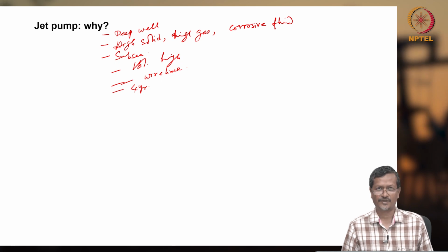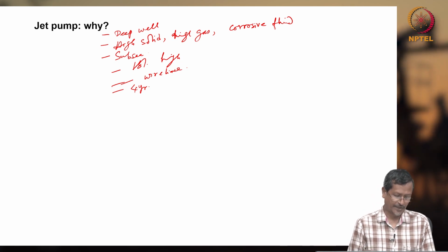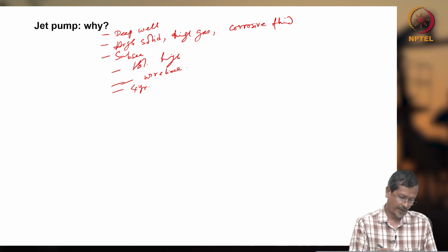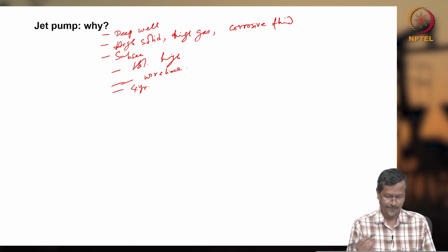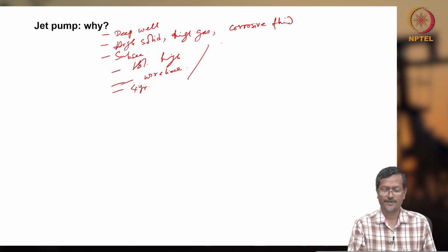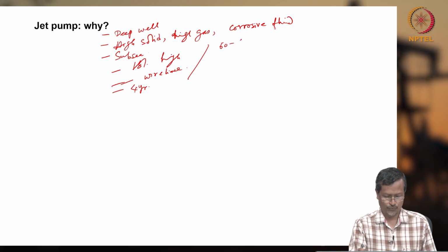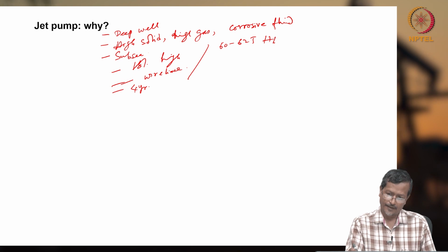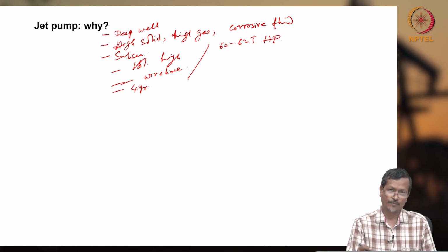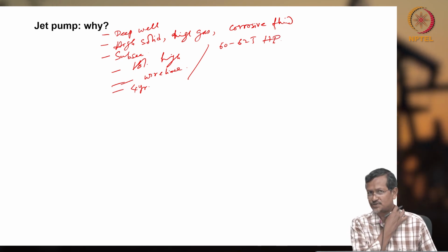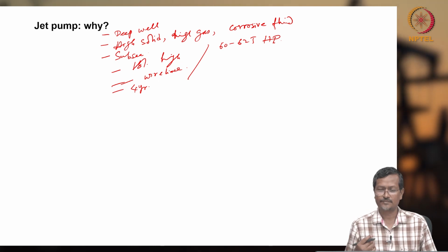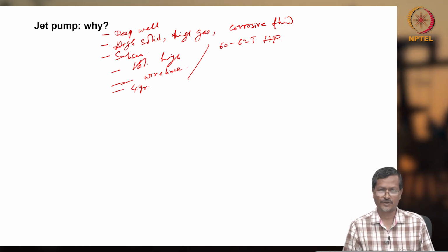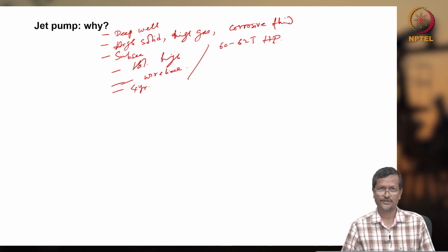Here you are saying about 4 years, a very long operation life. It will have surface equipment like a multiplex pump, and an electric motor or multi-cylinder IC engine can run this pumping system. We cannot say compressor, because you are not compressing; rather you are creating high pressure.